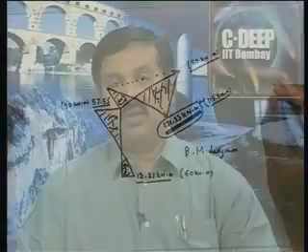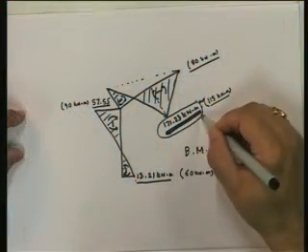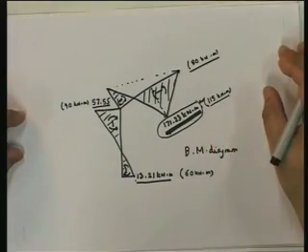So in other words, you see what's happened. Making the structure more flexible does indeed increase the displacements and reduce the member end moments. However, if any structure has a load on a member, then this is not a good idea, because we'll see what happens. The maximum bending moment in the member goes up significantly if you have a member loading.